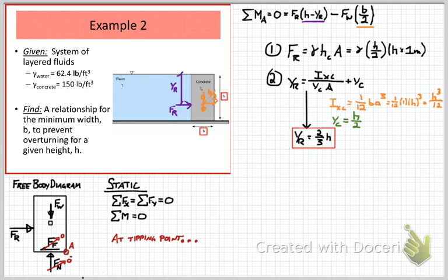This is actually a generalizable result for us on a special case where we've got a vertical surface. If you look down at the free body diagram, I filled some dimensions in. For a case where we have a pressure prism that originates at the surface on a vertical wall, that resultant force will always act 2/3 of the way down and 1/3 of the way up. So you can use that as a shortcut as opposed to having to go through the steps that I've shown in orange and green on your current slide.